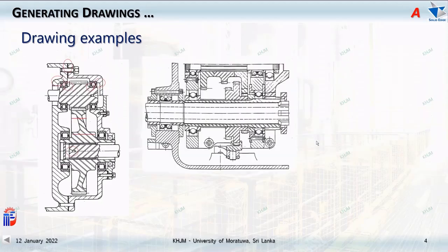And there is another one you can see over there. In that case also, you can see this is a double row angular contact ball bearing. So depending on the bearing, the mounting arrangements can be different. Certain bearings like angular contact bearings and others need preloading of bearings.